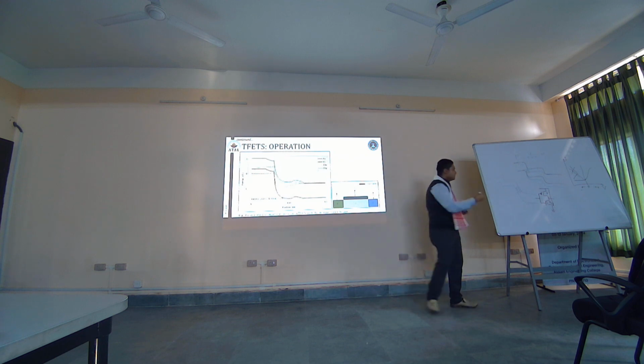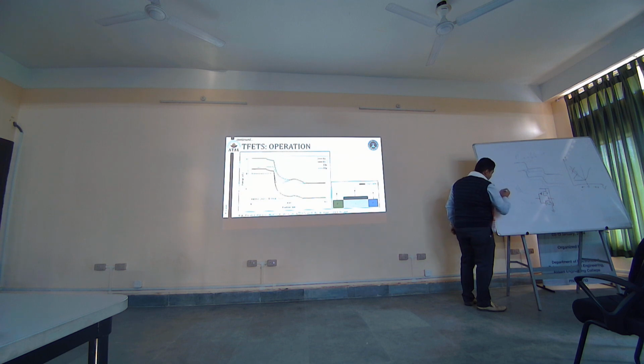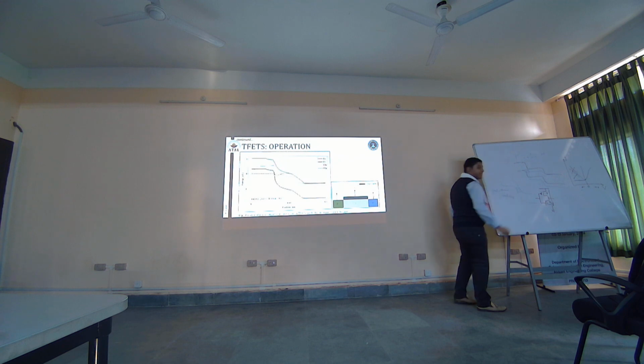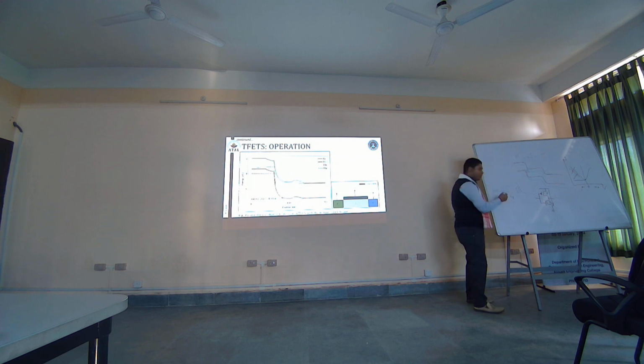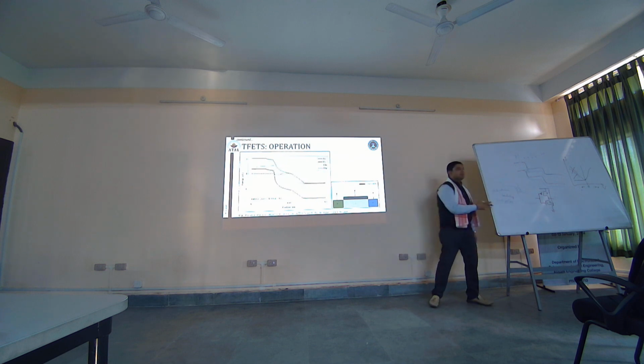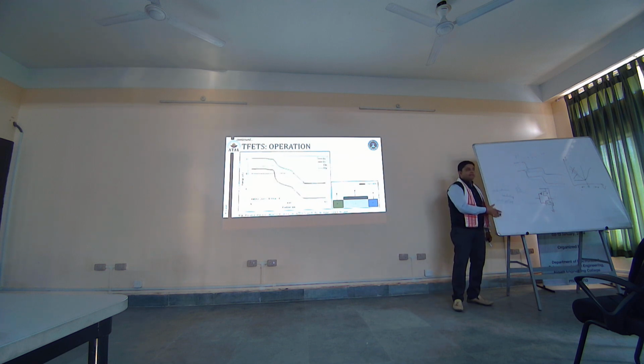This is known as the gate drain underlap. Okay, and this is one of the very widely used techniques to reduce this negative half of current, which is also known as the ambipolar current. Ambipolar current in TFETs. So this is one of the disadvantages of TFETs, and this is how we remove them. I think the explanation is clear. The connections are clear.